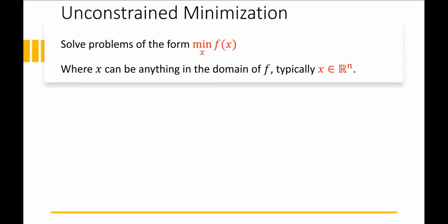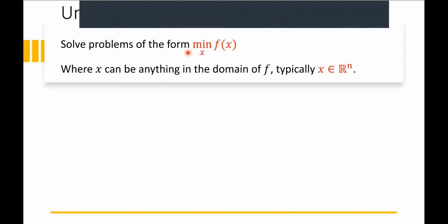So you are given some function, f of x, let's say, and in this case, f of x could be the distance of motor configuration x from the ideal configuration. So f of x is the distance between the forward kinematics solution for motor configuration x, like where my end effector is for some motor configuration I choose, away from where I actually want my hand or my end effector to be. So this says that I get control over what that x is, right? I want to find the joint configuration that minimizes this error function. And usually in this case, our x is just some real valued vector. That could just be one entry for each of my motor joints.